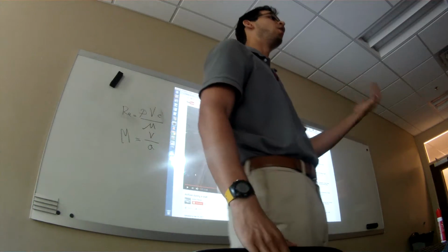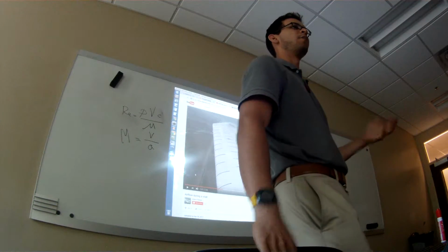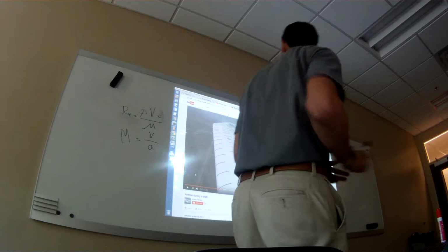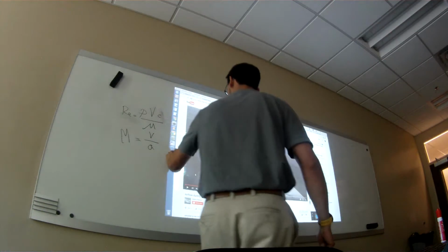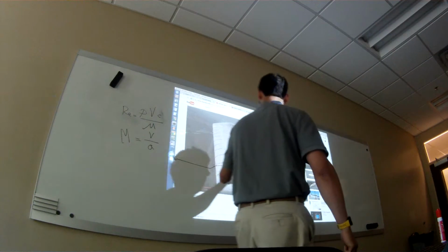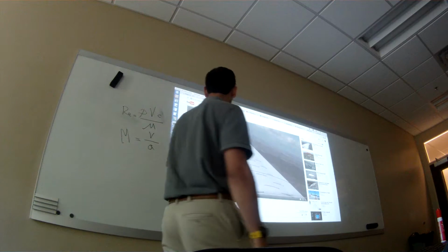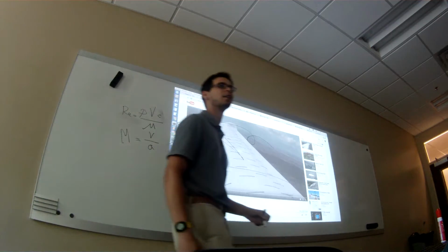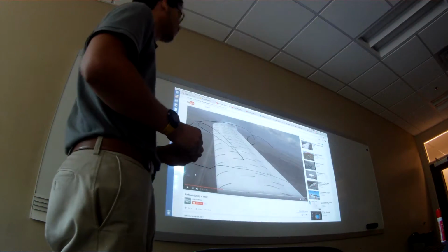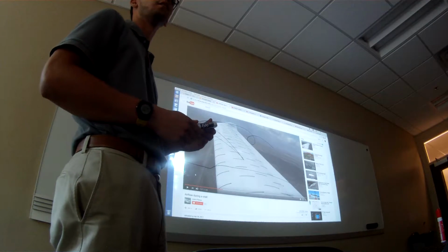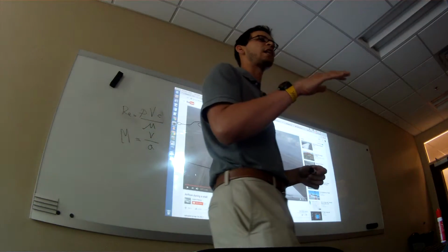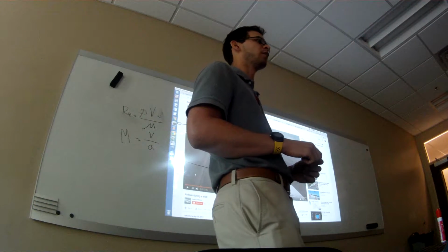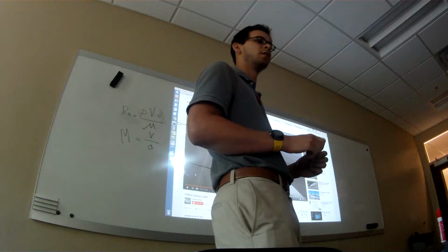So you might think, oh, if I get an angle of attack of say 20, then I'll be fine. You can't fly at an angle of attack of 20. The flow won't attach, right? If I'm an air molecule here minding my own business, I want to just travel over like this, no problem, right? You give me an airfoil that looks like this, and I'm going to say no way and do this, right? So you can't fly at an angle of attack that large. Make sense? If you get a cruise angle of attack of like 8, I'd be a little concerned. You want like 3, 4, 5 maybe for a cruise angle of attack. The angle of attack you need is not that large.